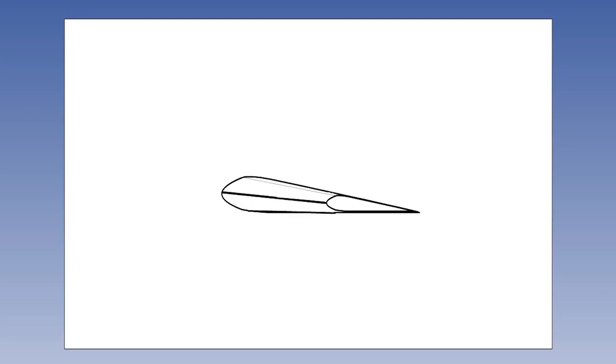features described next. The wing can be designed with a twist which reduces the angle of incidence, the angle between the mean chord line and the fuselage datum line, towards the tip. This is known as washout, and decreases the angle of attack at the tip relative to the root, and the root will tend to stall first.